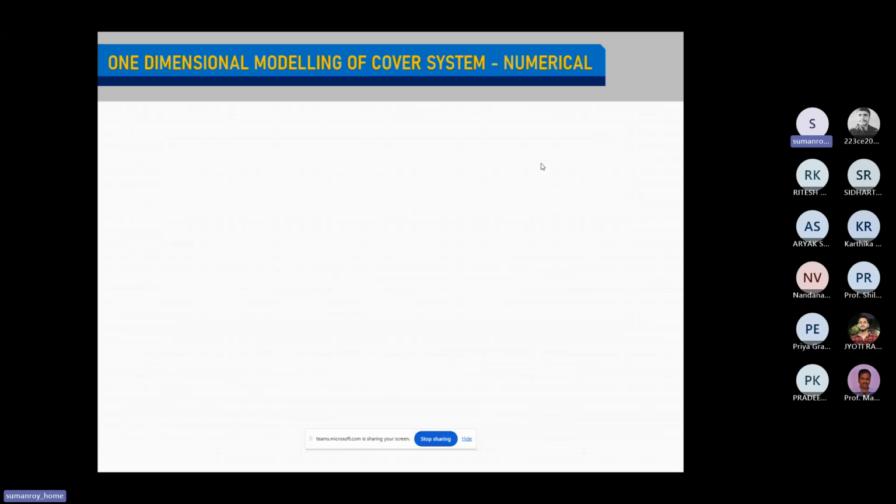So the last and final part is how to check that these two systems are working, whether the cover system is perfect or not: testing under real life conditions. We know right now that on the strength aspect, 100 bentonite dominates over 20 bentonite 80 sand. On the volumetric aspect, 20 bentonite 80 sand dominates over 100 bentonite. But there is a distinctive difference between their permeability. One of them is at 10 to the power minus 12, while the other is at 10 to the power minus 9.